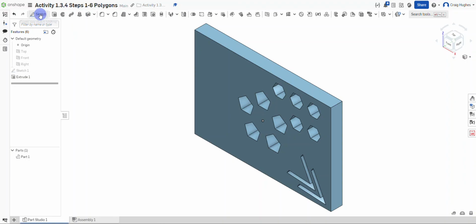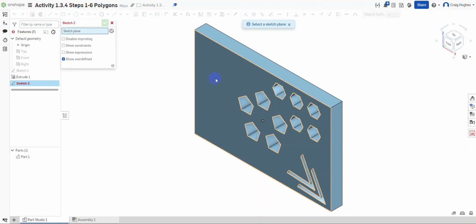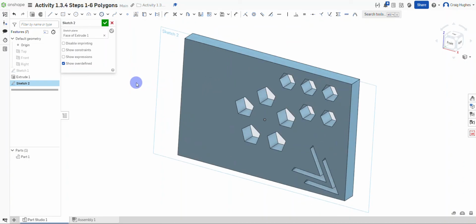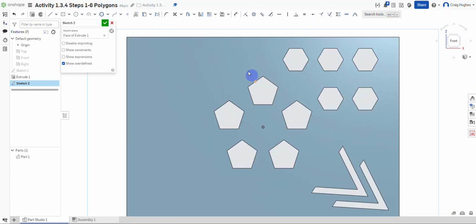So I'm actually going to create a new sketch on this flat surface of our part. I'm going to press the N key on the keyboard to turn this normal. The project tool is up here, it's down here. They actually have it called the use. It's also use, project, convert. So I'm going to go ahead and select that option.